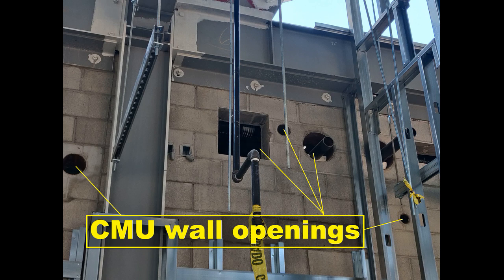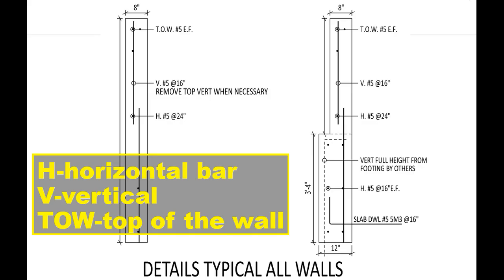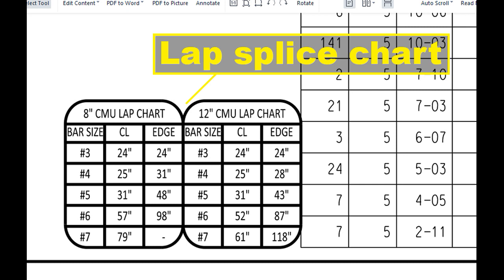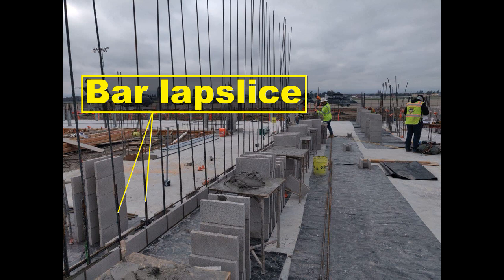Provide wall elevation drawings with minimum scale of 1/4 inch per foot. Submit drawings including plans, elevations, and details of wall reinforcement, details of reinforcing bars at corners and wall intersections, offsets, tops, bottoms, and ends of walls, control and expansion joints, lintels, and wall openings. Form splices by lapping bars as indicated. Do not cut, bend or eliminate reinforcing bars. Foundation dowel bars may be field bent when permitted by construction officer or building official.